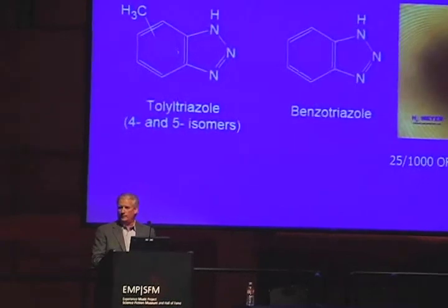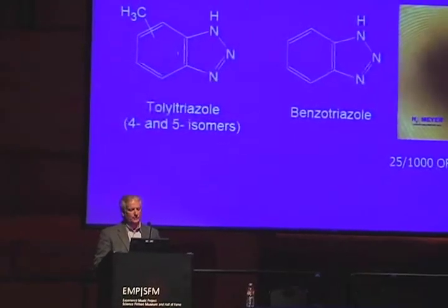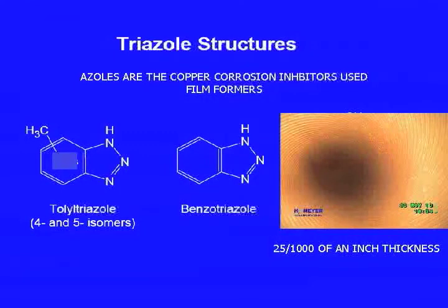One of the copper corrosion inhibitors is azole. This is basically a film former. For all your chemistry guys, I gave you the 2 molecular chemical formulations right there. Basically, there's 2 types: tolyltriazole and benzotriazole. This is added in the chemical and puts a molecular level coating on the copper surfaces and acts as a barrier. So really the corrosive water doesn't come in contact with the pipe surface itself. And we normally want to carry about 1 to 2 parts per million of azole in the system.